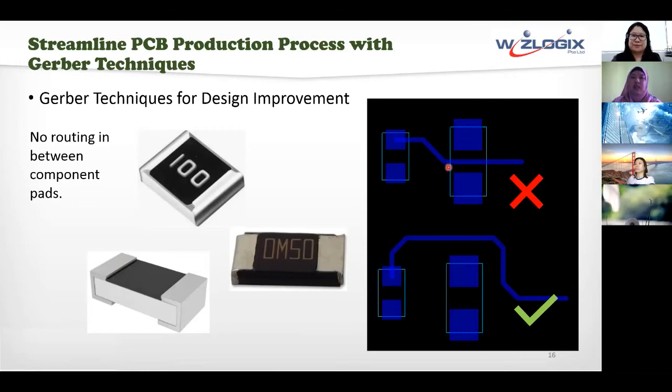in between. And then also solder mask or PCB board, after many rounds or many years of use, there will be wear and tear on the solder mask area, especially where components are loaded in. So potentially solder mask can be removed either by years of use or by the heat generated by the component itself, exposing the copper trace here at the center. We definitely want to avoid this kind of scenario. So what we do is normally we try to avoid and route out of the component itself.